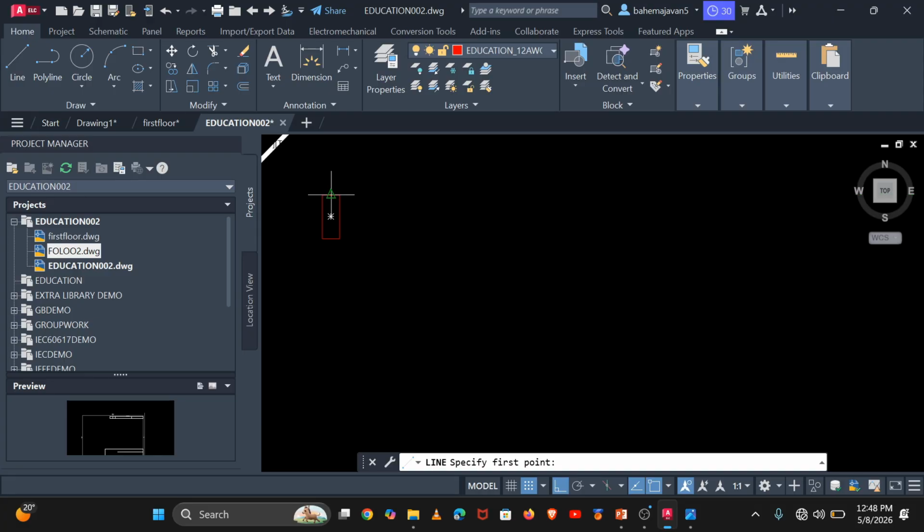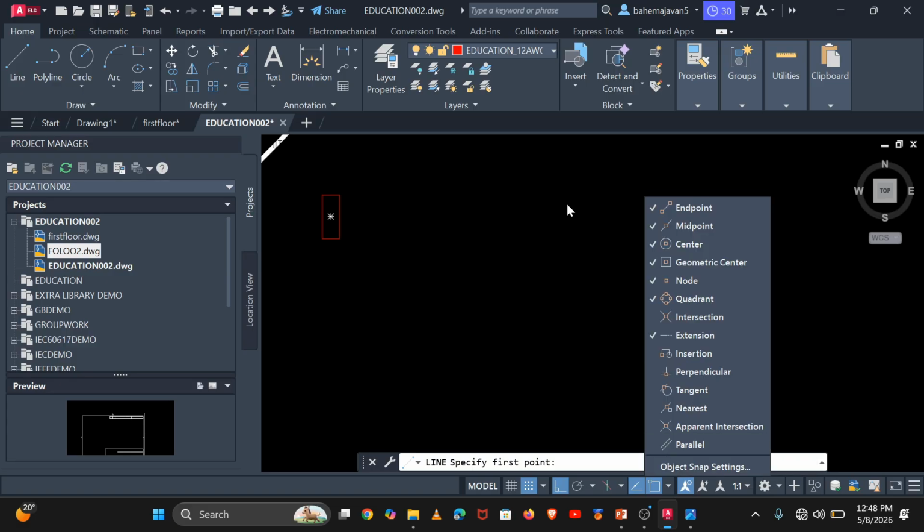This happens because we have this snap cursor to 3D reference point on, and by drop down you can see you can snap on end, midpoint, center, geometric center. So we must reference by beginning the center of any given drawing that we are going to draw, so that we draw a perfect thing.